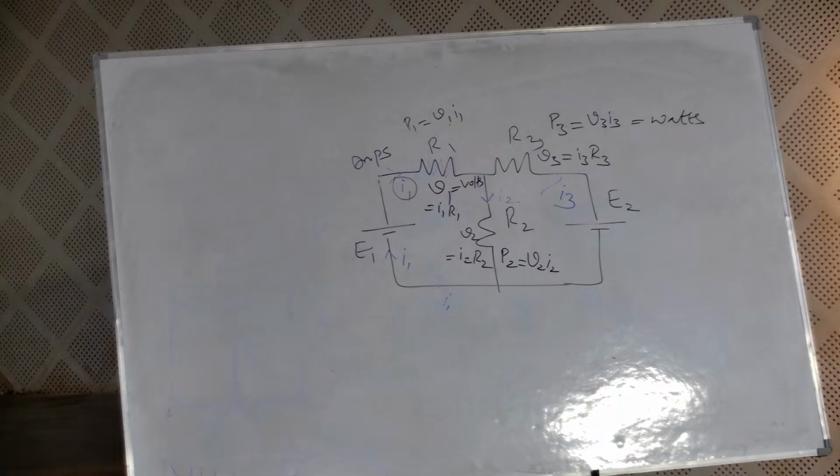I will give you a problem, and we have to solve it. So what methods are we using here? Mesh method and nodal method. Get the branch currents first. Then automatically we get voltage drops and power taken. You can apply any one method, and you will get the same answer for any given circuit.